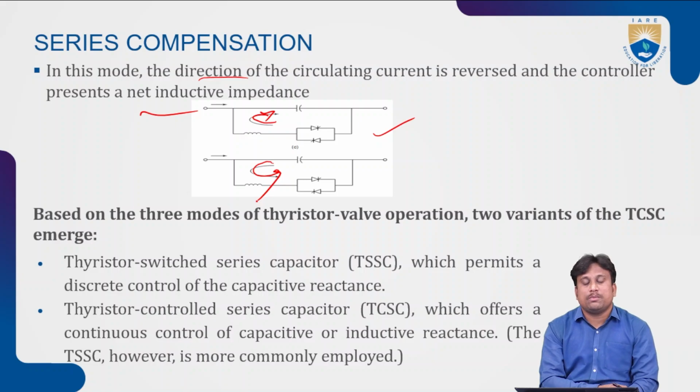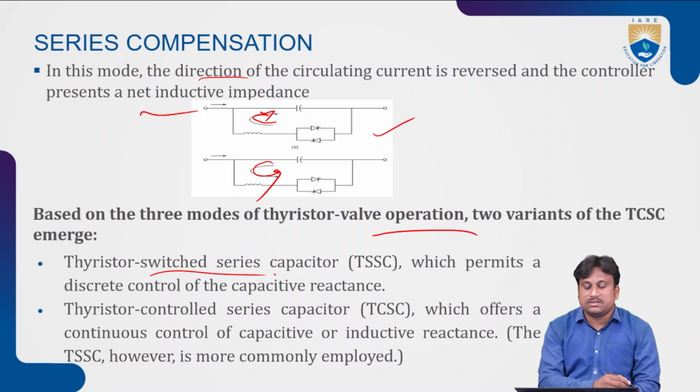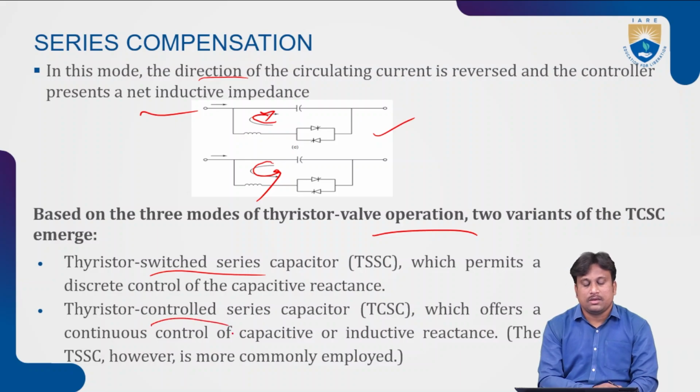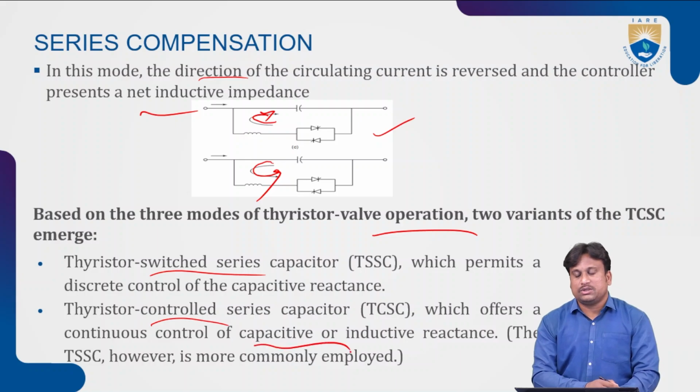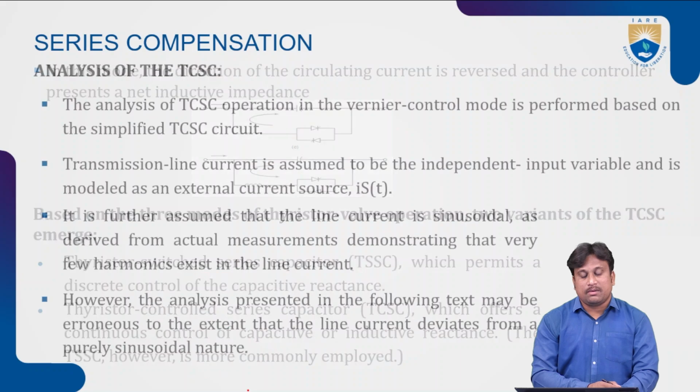Based on the three modes of thyristor valve operation, two variants of the TCSC emerge. Thyristor switched series capacitors permit a discrete control of the capacitive reactance. Thyristor controlled series capacitors offer a continuous control of capacitive or inductive reactance, and are more commonly employed.